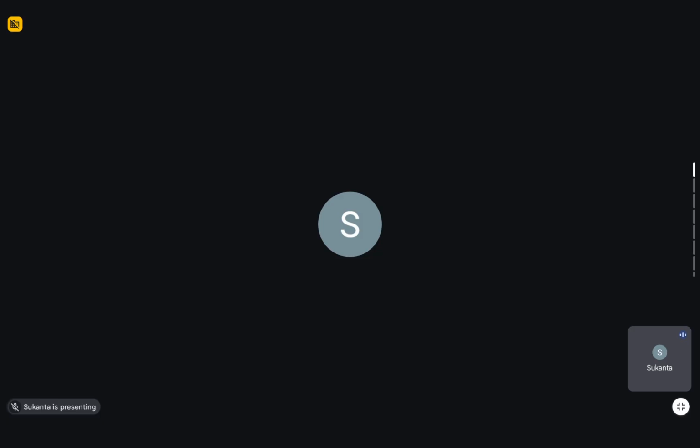Here is the carbon nanotube junction. This is one carbon nanotube, this is the junction, right? Here is the schematic diagram. We use conducting AFM. The tip is conducting. We measure resistance by IV using conducting AFM.